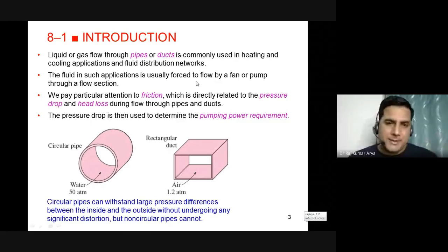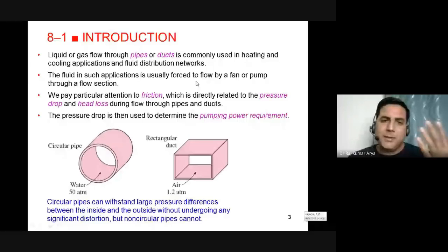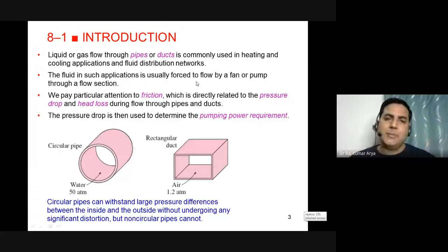In the case of water pipelines in populated areas, most of the time concrete pipelines are preferred, because you maintain the temperature inside the pipe, avoiding excessive cooling or excessive heating. All pipelines are buried inside the ground with a cover of, let's say, 2 to 3 feet.